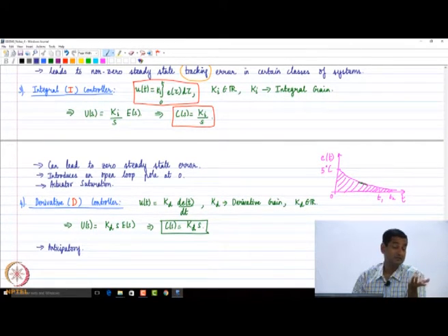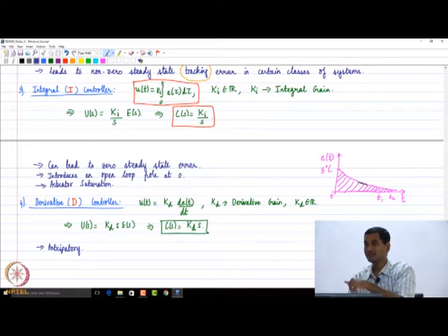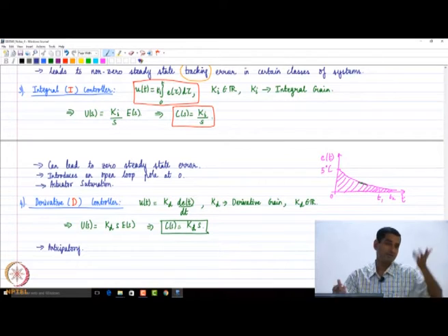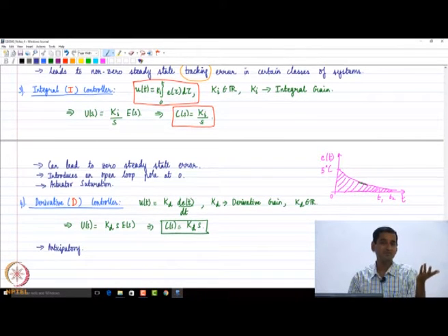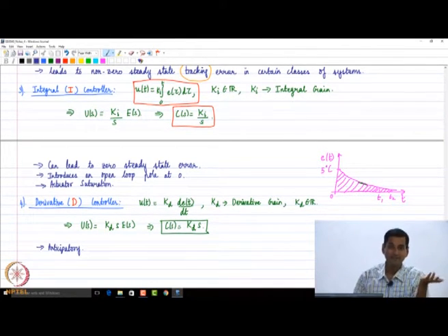Let's say if the error is going to increase a lot, then it may take action now itself, so that it will not allow the error to increase beyond a certain limit. If we know that the error is on a downward trend, then I will progressively reduce the control input. Why should I do that? Control input has to do with cost, ultimately, in real life.